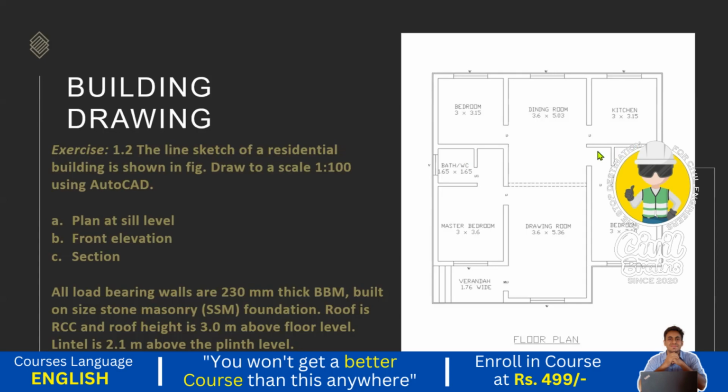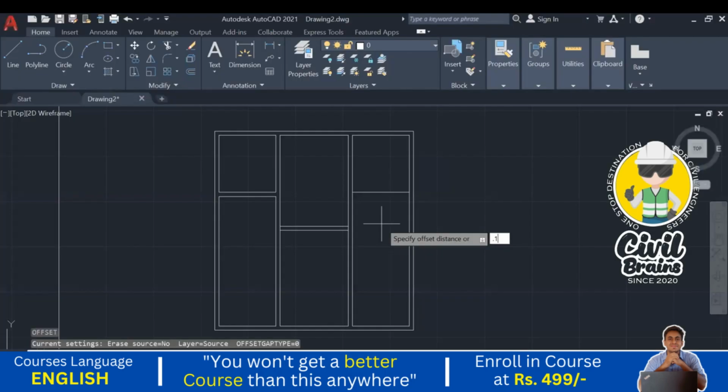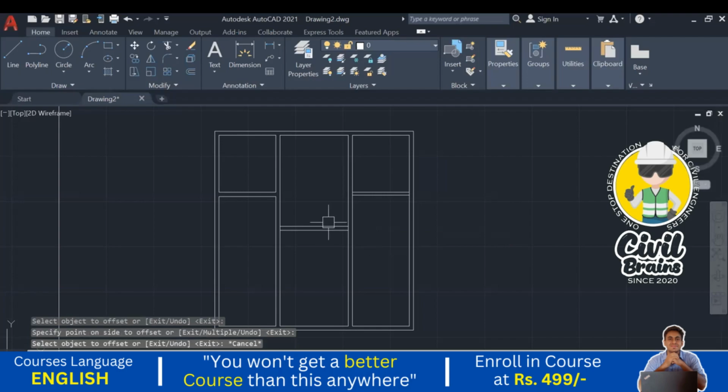So what is mentioned? That is a partition wall. We are considering in this particular plan that it is 150 mm. Okay, 150 mm I just consider. Just go here. Offset I have taken 0.15. Press enter. Press enter. Okay, so 1, 2, 3. These 3 rooms are ready.